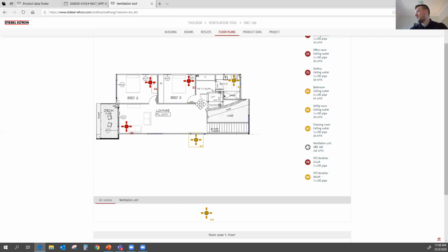Do not think that this is a good job I'm doing right now. It's just for illustrative purposes. This is not how we do it. But essentially, we would supply and extract. We would put these valves in the right spot, taking into account the draft, taking into account if we have multiple stories, balancing, making sure we're not supplying too much upstairs, too little downstairs, or have a very drafty staircase.